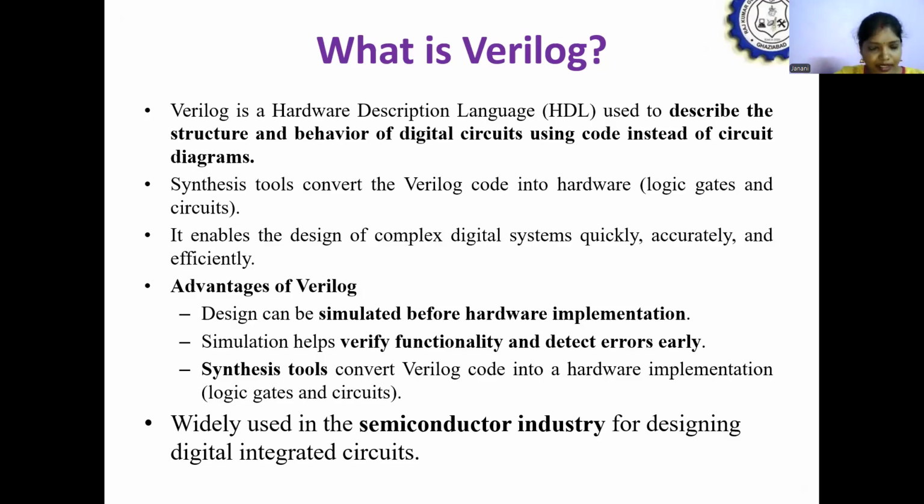Once the code is written, we use a simulation tool to verify the function of the code. Once it passes all the simulation tests, next we use the synthesis tool. The synthesis tool converts the Verilog code into the gate level netlist.